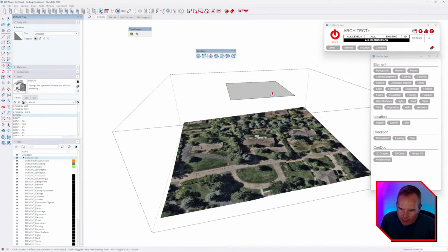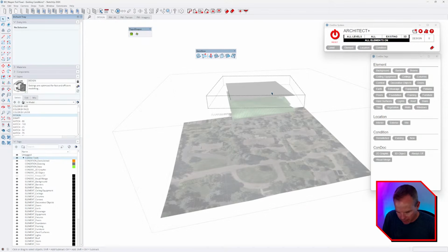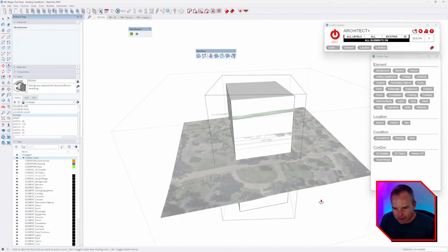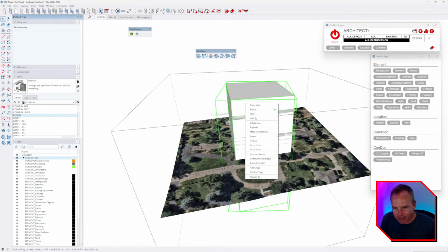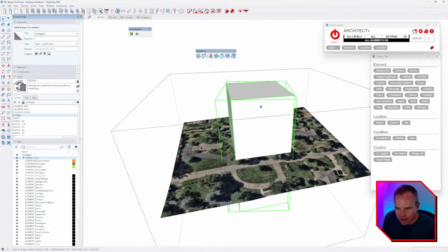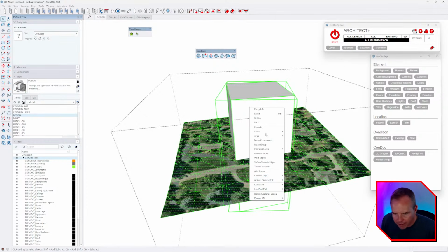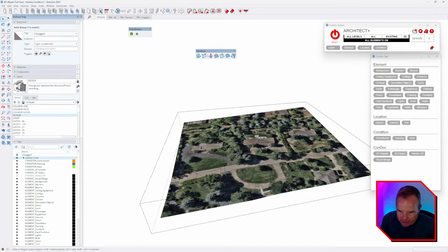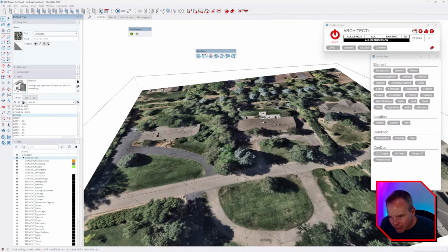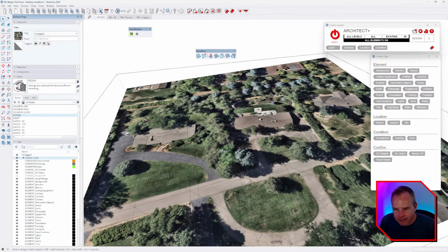Actually, I won't explode that. I'll just jump in and then pull this down, and then I'll back out of here and intersect, hide rest of model, intersect faces with, I'm going to select all and intersect faces with selection. Let's see if we get a better, yeah, see, drape didn't nail it. And so now, you know, that intersect worked better.